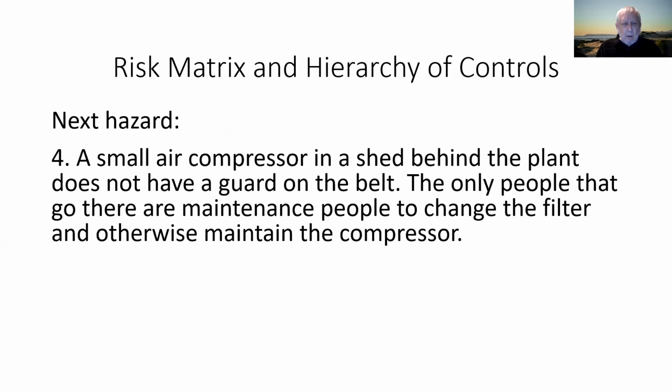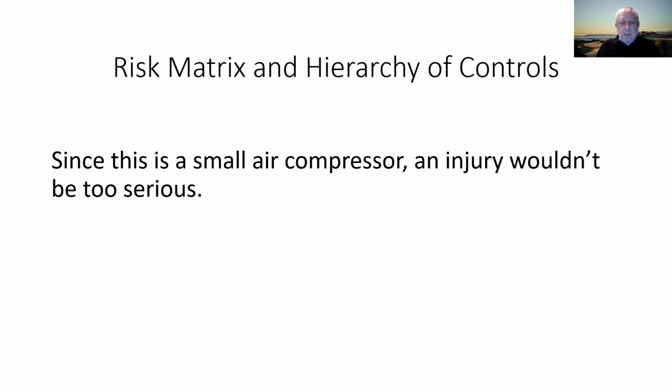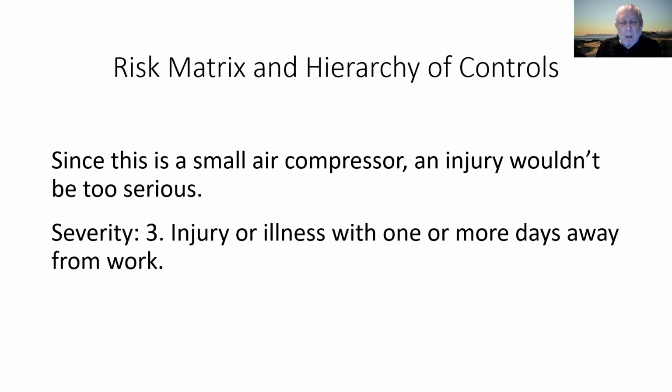Okay, the next hazard. There's a small air compressor in a shed behind a plant, and it doesn't have a guard on the belt. The only people that go there are maintenance people to change the filter and otherwise maintain the compressor. It's a small air compressor, so an injury wouldn't be too serious. It wouldn't rip your arm off or anything like that if you came in contact with it. So the severity is 3, injury or illness with 1 or more days away from work.